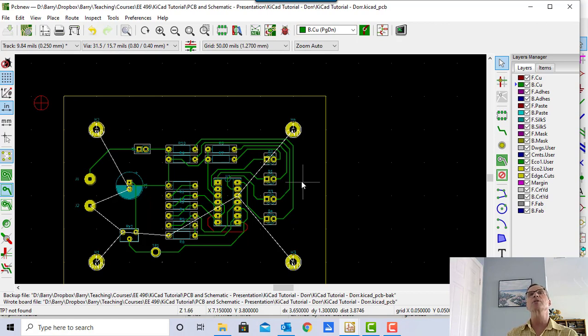In other words, we start off with fiberglass sheets that have copper on both sides, and then we use a mill to mill away all the copper we don't need. If we have to mill away all the copper over here, we're going to go through mill bits like crazy. So if you submit a board to Mark and it doesn't have ground plane on it, he'll ask you to go back and redo it.